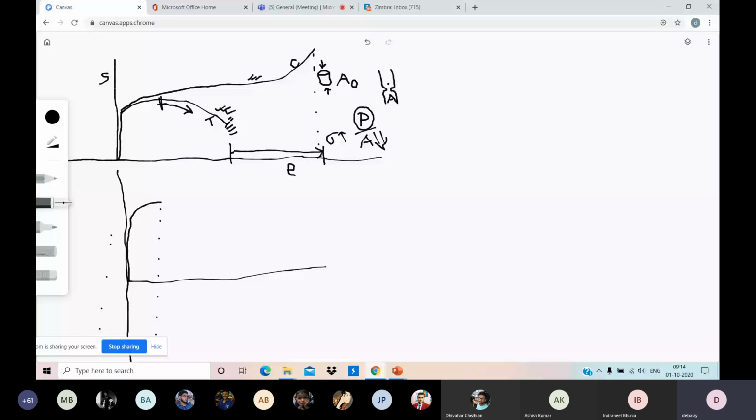At a very rapid rate, cross-sectional area decreases because the stress becomes high due to the low cross section. So in tension, the problem is necking. By the process of necking, localized deformation happens, and every deformation is happening in one region. Cracks, voids form, and voids grow and voids coalesce, and then a crack forms, and then the crack leads to failure. But in compression, necking doesn't happen.